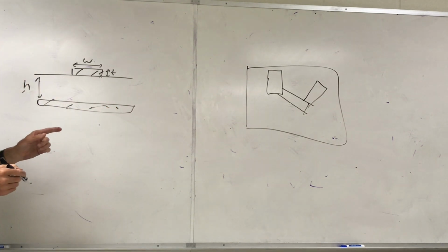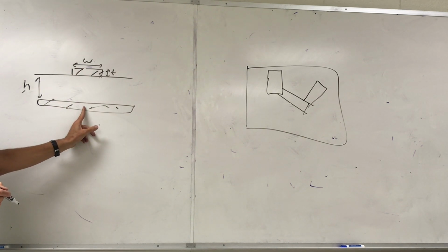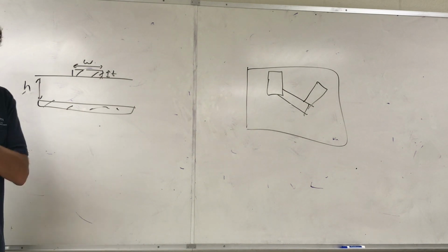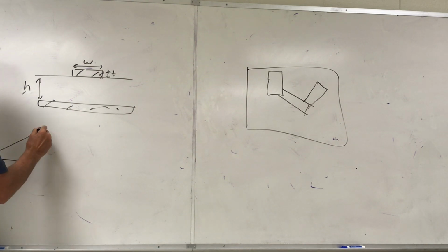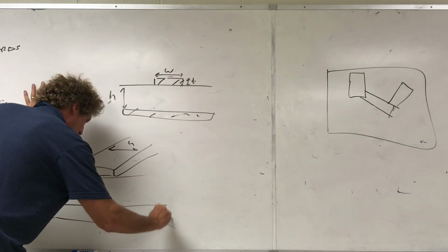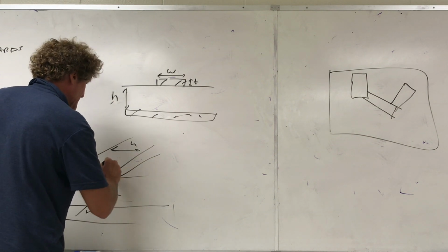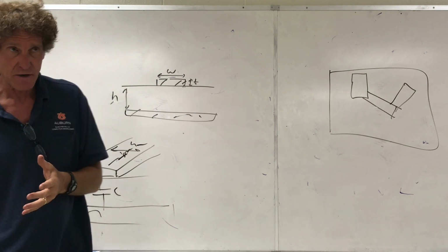What this is, is a transmission line. Between here and here is a plus-minus conducting path. Are you with me? And it looks like a transmission line. Not a coax cable, but it looks like a transmission line where the top has a certain width here, and then there's that dielectric. And then down here, this is all copper. And effectively, there's a capacitance between them, and there's going to be a series inductance with these things. So it is a transmission line, is what I'm going to get at.